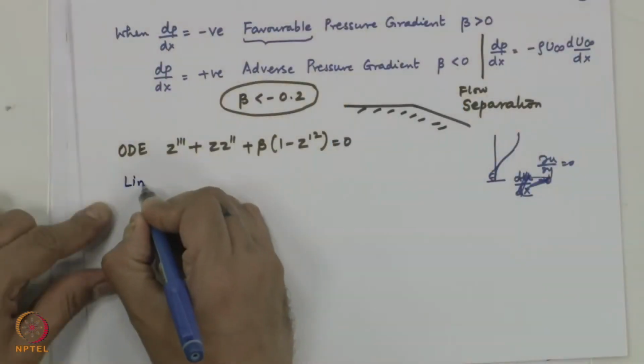So, the fluid is also subjected to a reverse kind of action, and the velocity of the flow is a direct indicator of the momentum. If you look at the left hand and right hand side of the Navier-Stokes equation, dP by dx is positive, so the quantity on the left hand side starts to go on decreasing, and you would reach a stage where the flow is no longer able to sustain itself, and you would see separation of flow occurring. So, this is a very, very important case, and this happens to be the limiting case